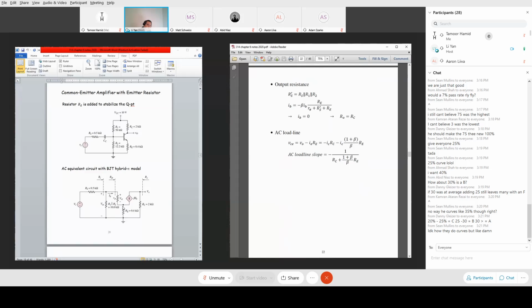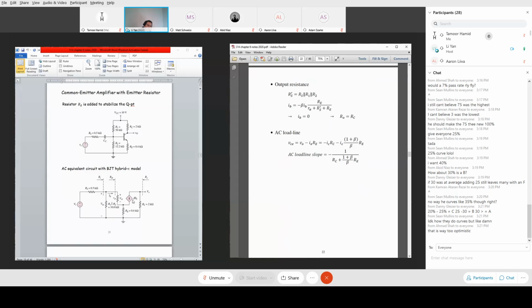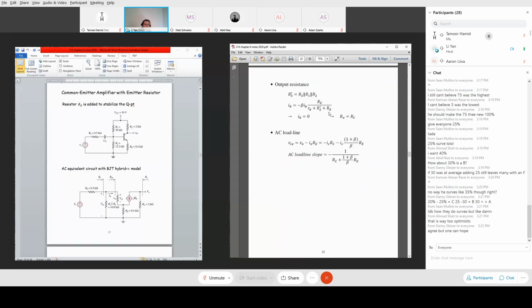And here is the current division issue. Current division is how much current I get out of this way, out of the total input current. So it says minus IB; I put the minus sign on the other side. Total current is beta IB, and the factor determining the current division is this branch of resistance RE divided by the full resistance RE plus R pi plus RS prime in the denominator. So this is current division: how much current I get in this branch out of the incoming current. So I derive this equation by current division.